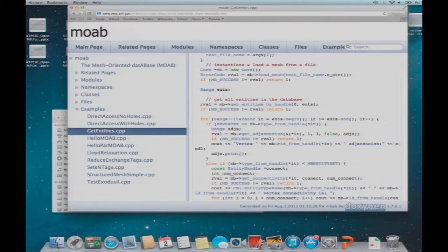And so we use a special handle of 0 to denote the whole mesh. And that kind of function allows us to not have a whole separate set of functions for interacting with an entity set. So when you want to interact with an entity set, you just give it the handle of the entity set, where if you specify that handle as 0, that means the whole mesh.